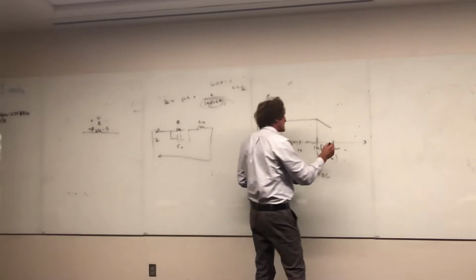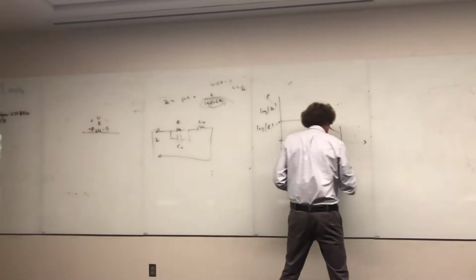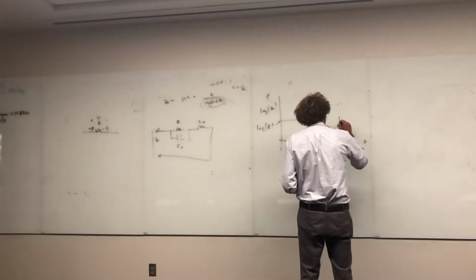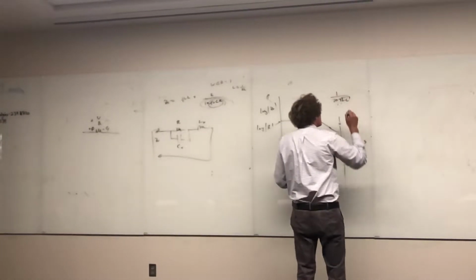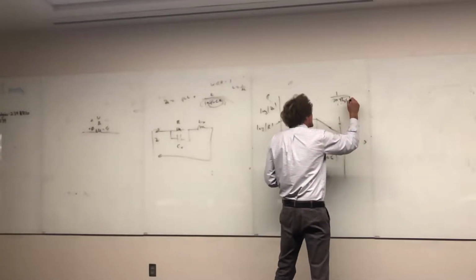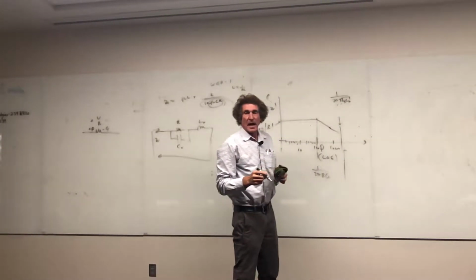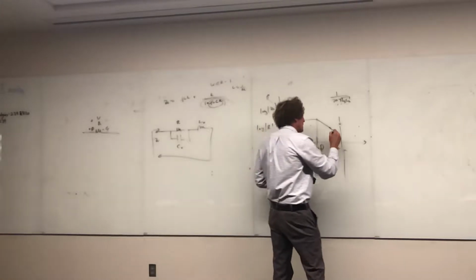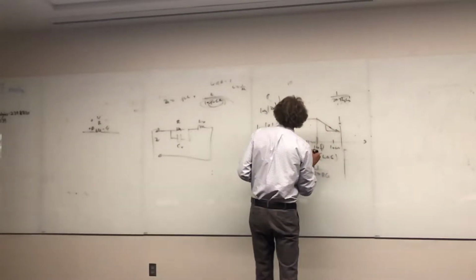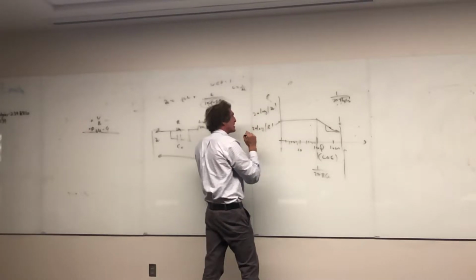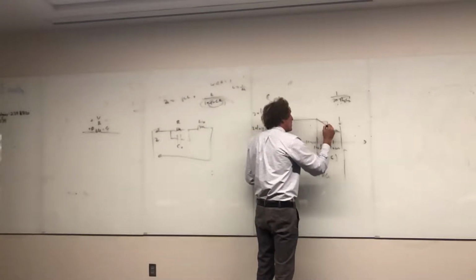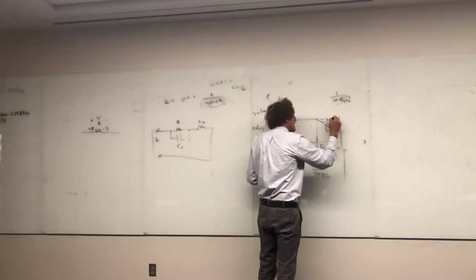It keeps going down at this rate until it hits this point, and this is going to be the resonant frequency, and that's just 1 over 2 pi square root of LC. You're familiar with resonance. This is XL, XC, right? And then after that, it starts going up at a rate, and the rate it comes down. Now, you can put the 20 on there, because I guess Wentworth's going to do that probably. This will fall at minus 20 dB per decade.